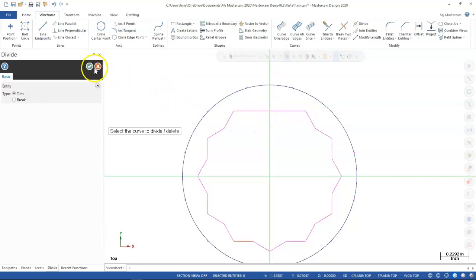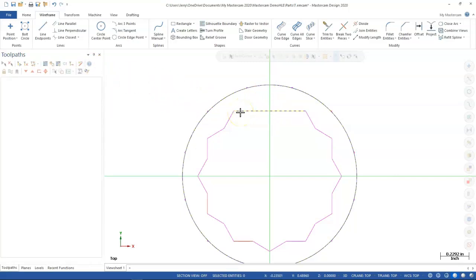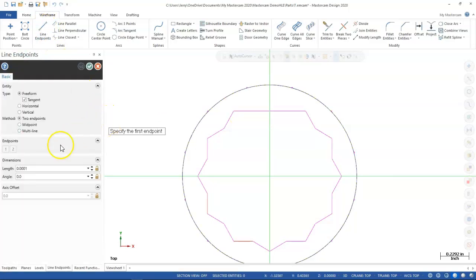All right, so the other item then will be to offset that line. All right, so if I go to a line segment, and let's see, we're doing freeform. Let's go vertical. I want to have a start point, so 268 divided by 2 will be 134. 134 comma 0. And then the endpoint just needs to extend past the line. And since we did a little bit with the extend before class, we'll come back and pick that one up.